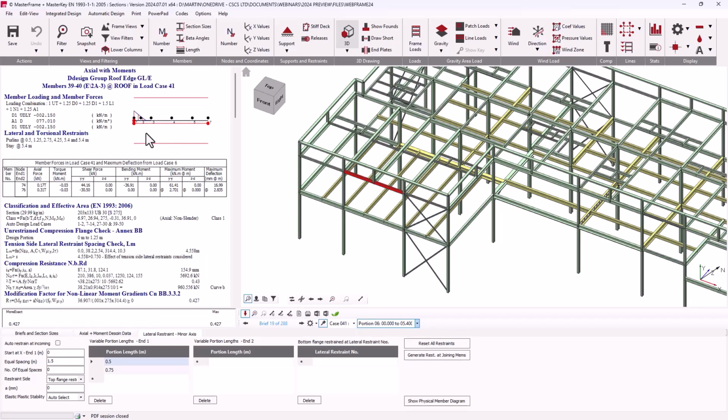So clicking below the line, selected the bottom flange portion of check, and we can see the check obviously is going the full length of the member because we don't have any restraint on the bottom flange. However, the program obviously, as the previous unrestrained compression flange check worked, looks at the portion of the member on which the bottom flange is in compression in accordance to the bending moment diagram. And the 0 to 1.25 that you're seeing there is obviously the point beyond the next restraint beyond the point of contraflexure, being the 0.5 plus the 0.75.